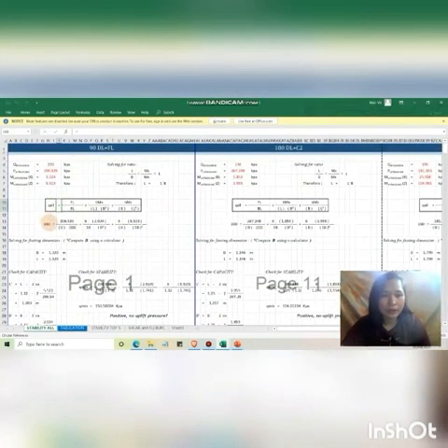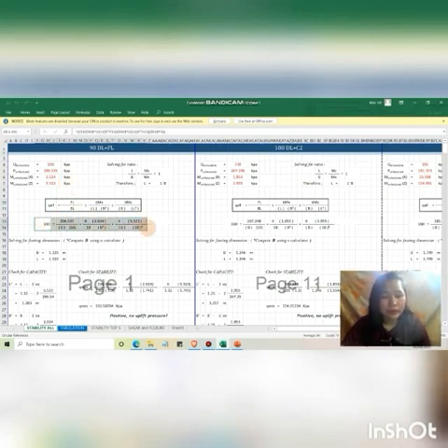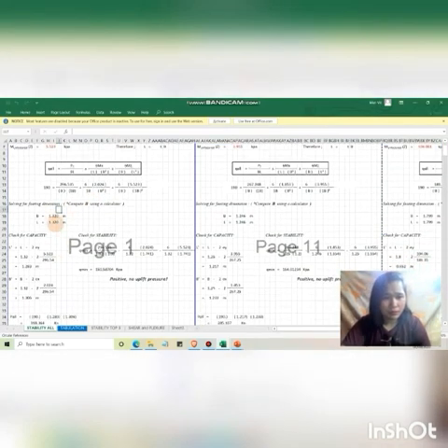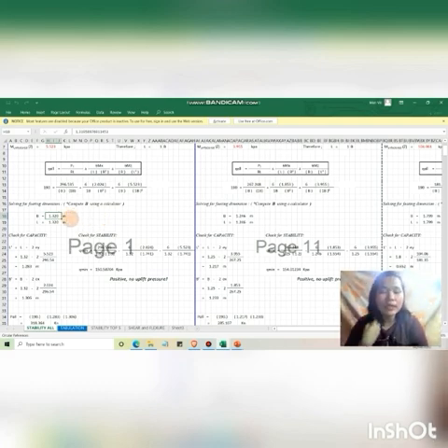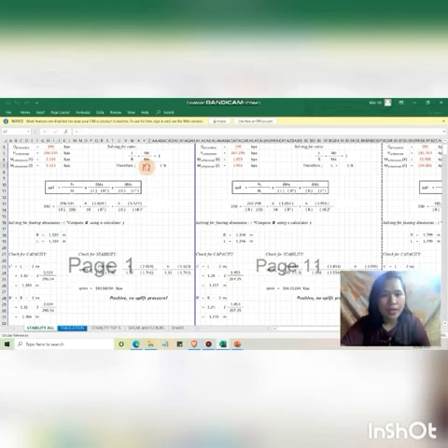Substituting the values of PY, MX, and MZ, we have this expression. Solving for the value of B, we arrive at this answer, 1.320 meters. Once again, our ratio of L to B is 1, so our dimensions for B and L are the same.